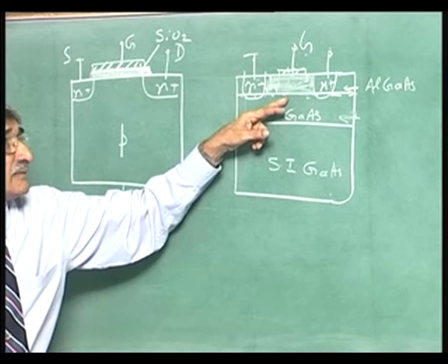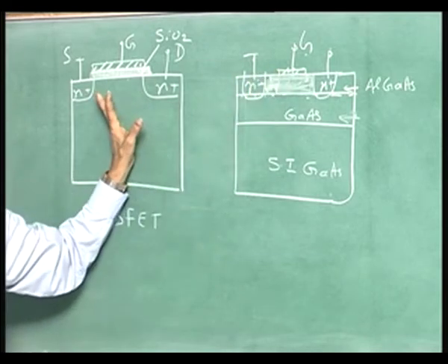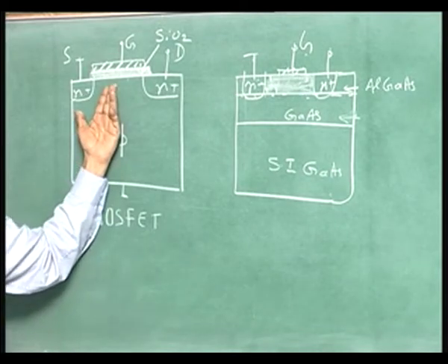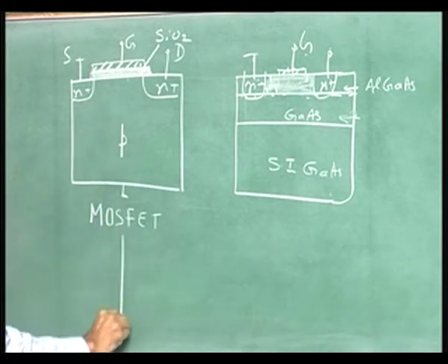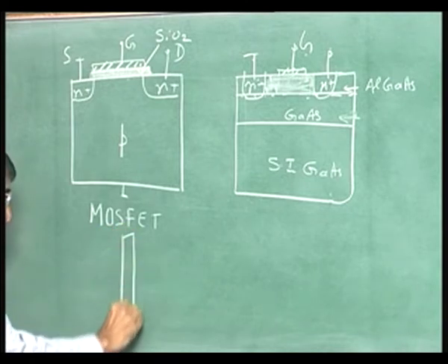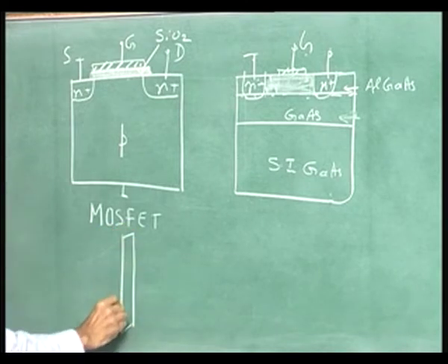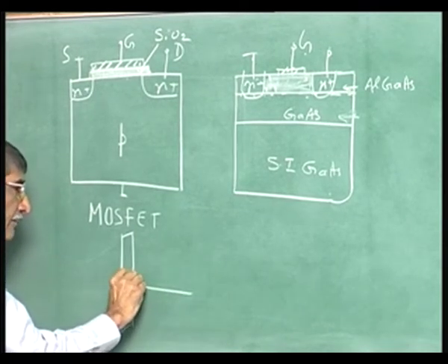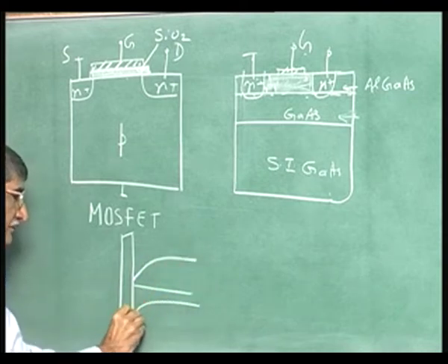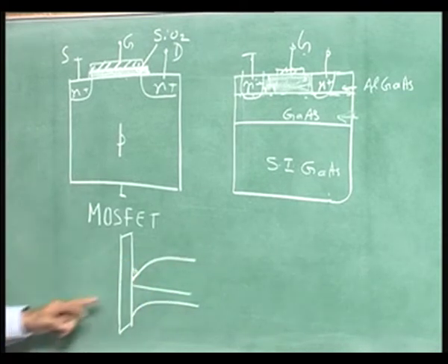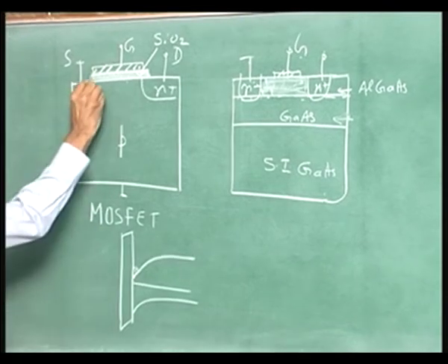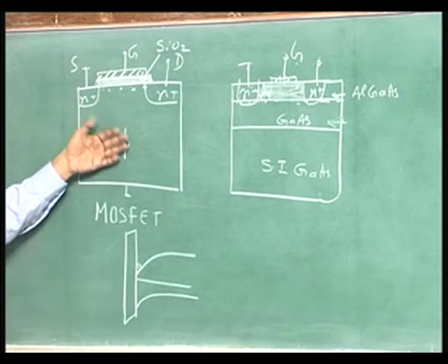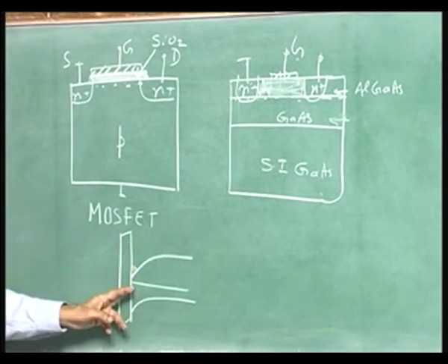The added thing here is that this is almost, or rather exactly, equivalent of this. You have got the notch here, which I have discussed earlier. Recall the p channel: that is the oxide, and then you have got the Fermi level and the band bending taking place like that. That is where the electrons are notched, held up. Those electrons are the inversion layer. Threshold voltage is the voltage at which the band bending is such that it becomes completely n type.